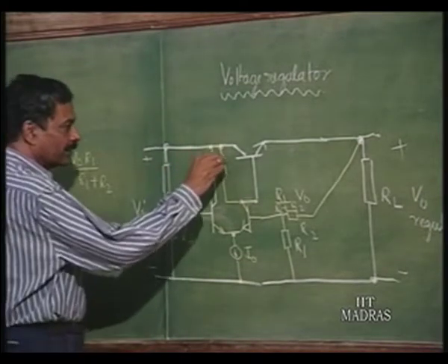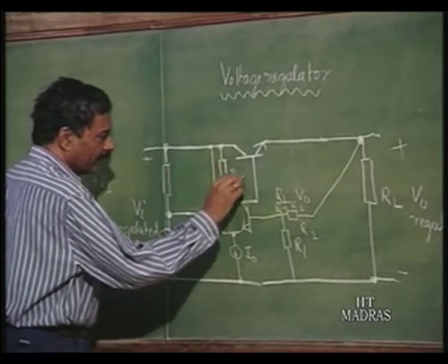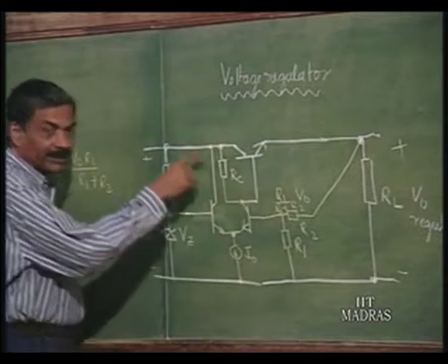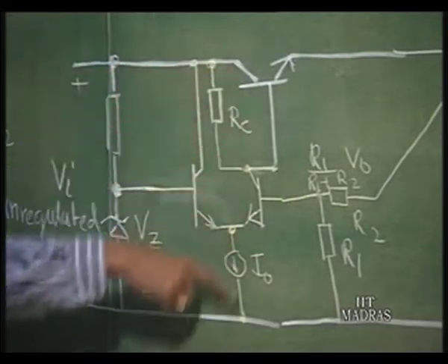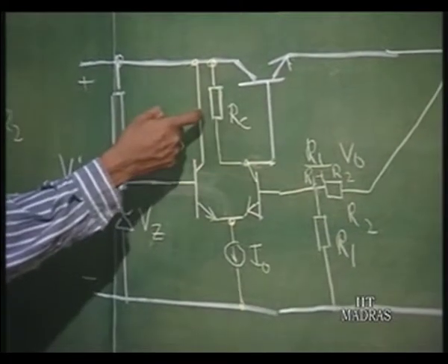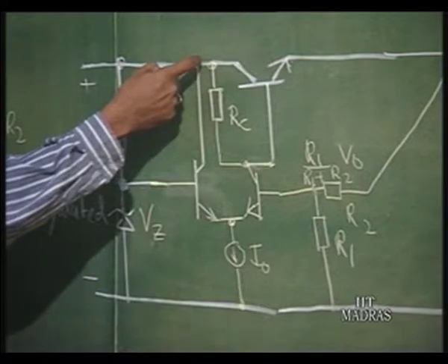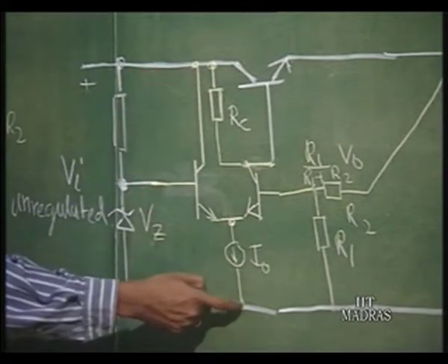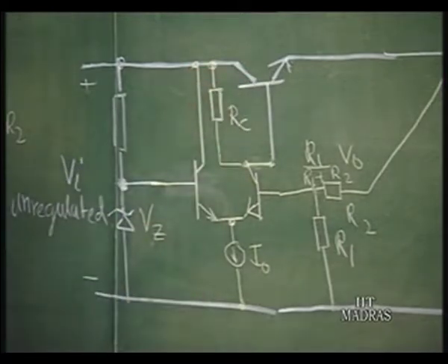So, essentially you can see that this particular structure is a very crude operational amplifier using a single supply. The input voltage itself is biasing this operational amplifier. So, one end of the op amp is connected to this supply and the other one is connected to ground. Okay. Output goes to the base of the transistor.